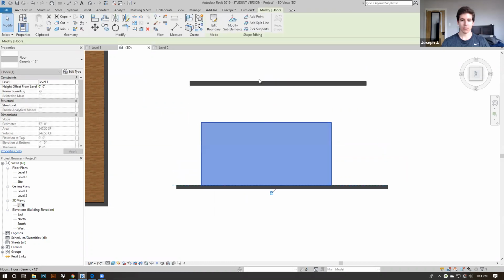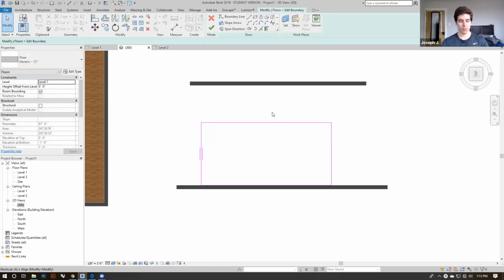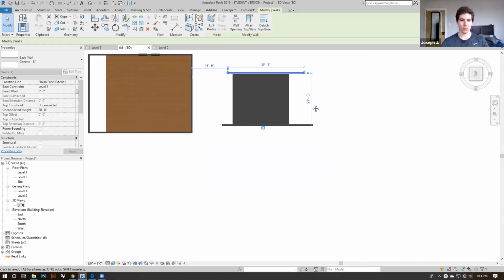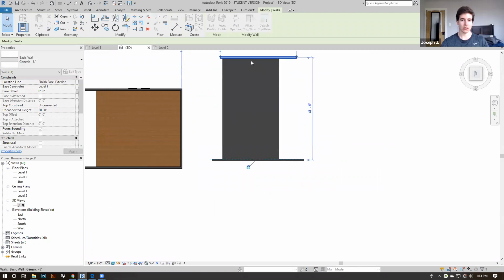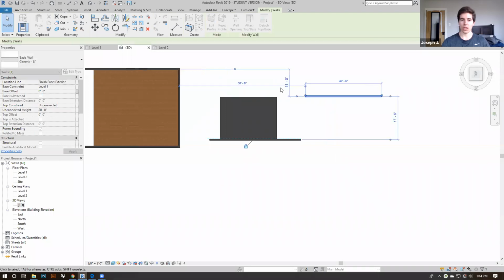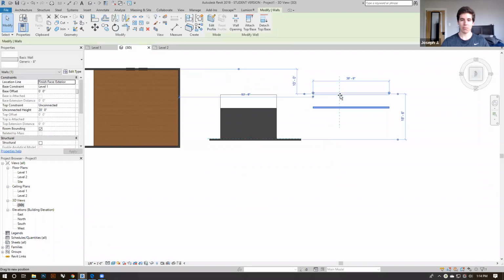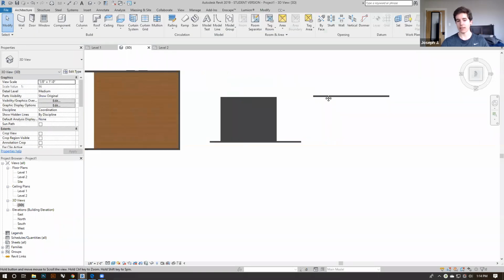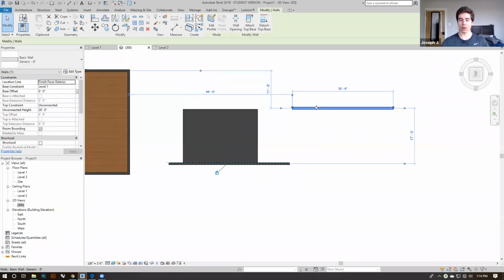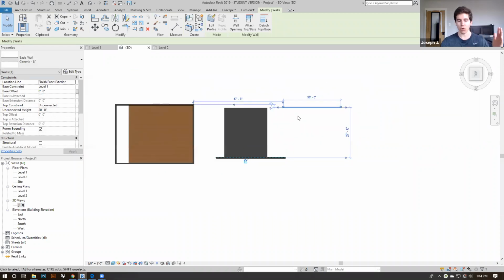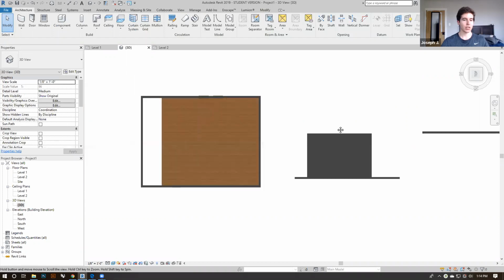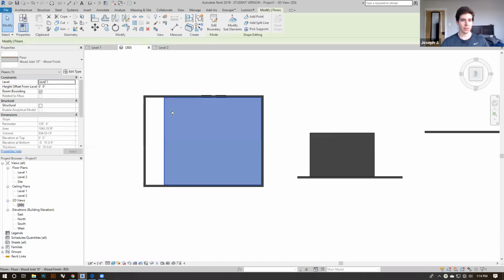Unlock it. And now I can stretch this, which is a nice thing. If I move this off the boundary, it will still snap. So it's good to make sure you don't accidentally align something to a part of your building that you forget, and then find out later that you're accidentally moving your whole building as you move a wall. Because Revit likes everything to be attached as much as possible. I'm going to fix this.